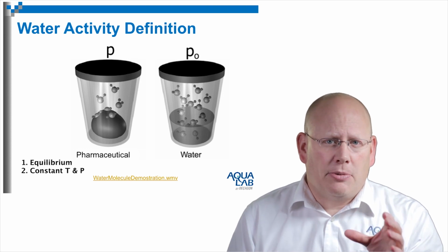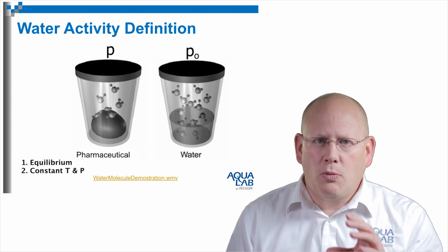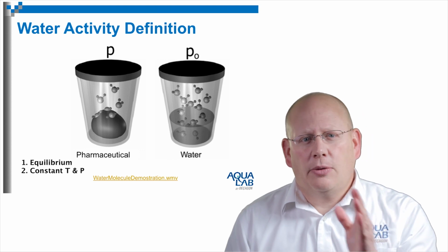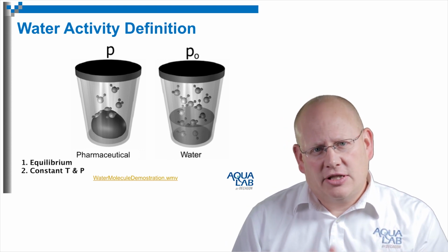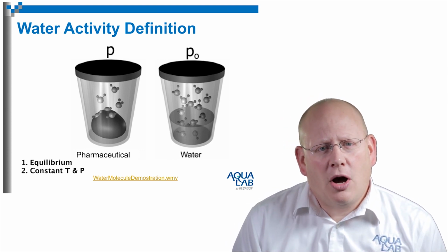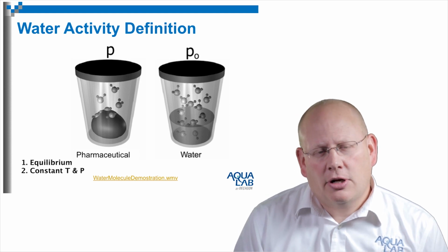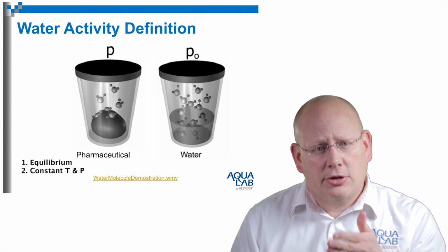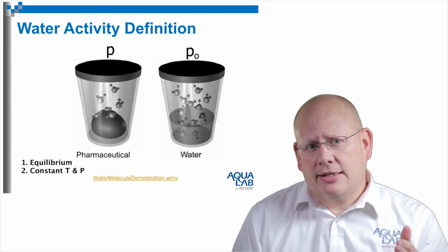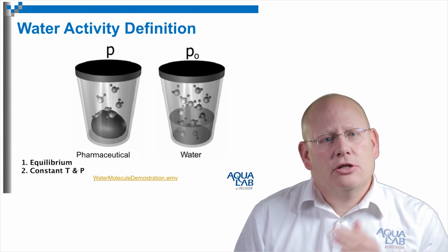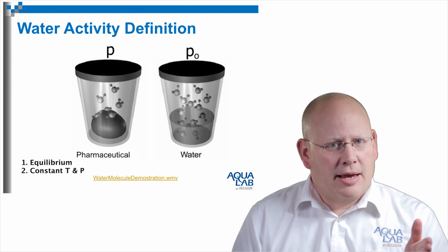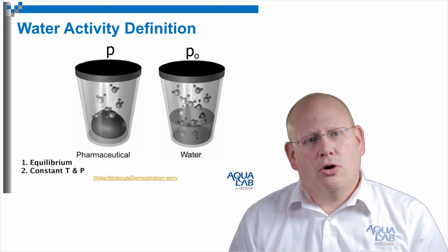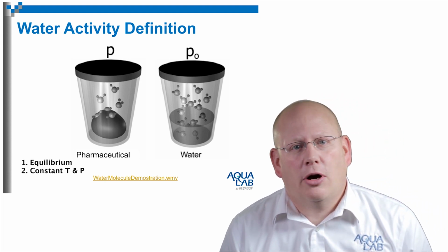If we take that vapor pressure, or we are able to measure it in some way and determine that pressure, and then we compare that, as you can see in the container on the right, if we had pure water at that same temperature in a container and sealed up, it would exert a certain pressure, the number of water molecules in the headspace being dictated completely by the temperature. So if we know the temperature that the sample, the pharmaceutical product, is at, then we can know what the saturated vapor pressure of water is.